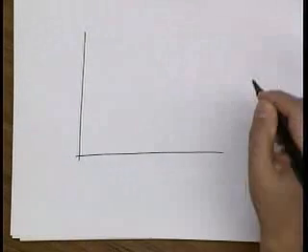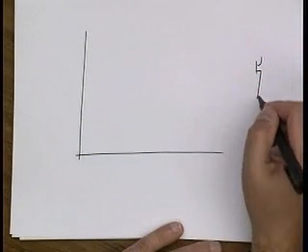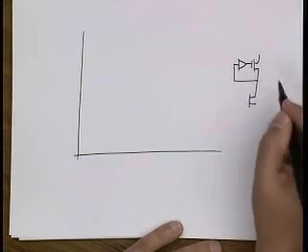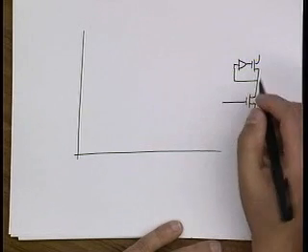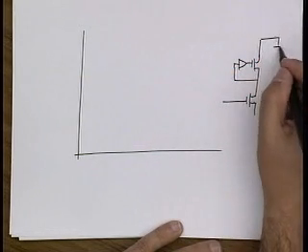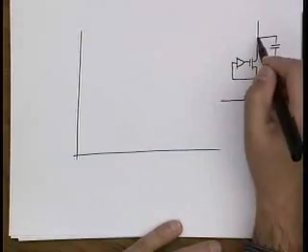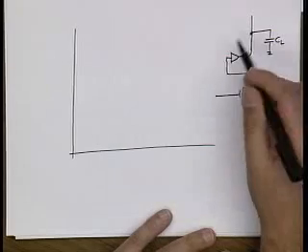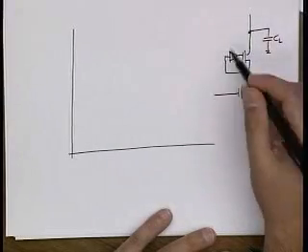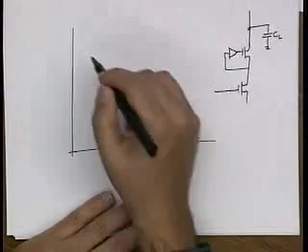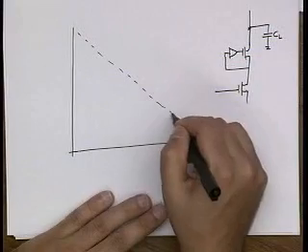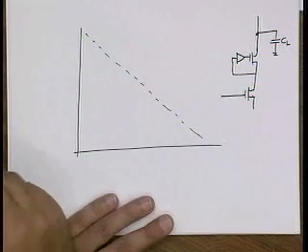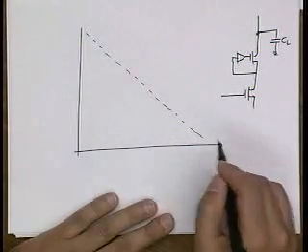The idea is if I use this gain boosting in an amplifier, then probably this is going to be some high impedance node at the output of my amplifier, right? So there's going to be some CL here. So in fact, if I look at the effect of CL, if I plot the impedance of CL on this graph here, ZL is just dropping, right? It goes to infinity at low frequencies, and then it just drops monotonically with frequency.